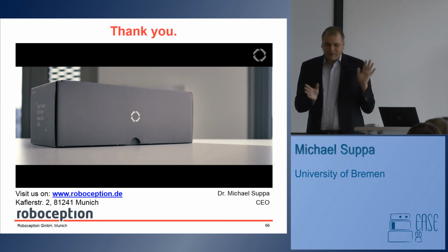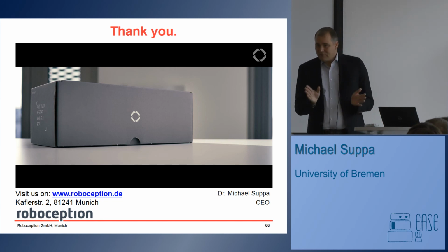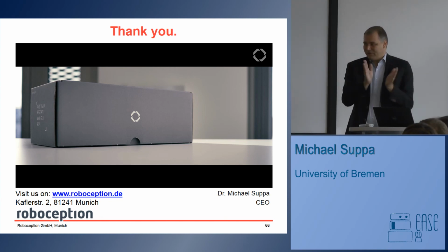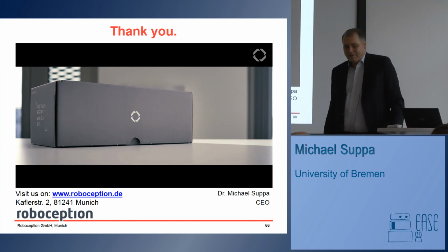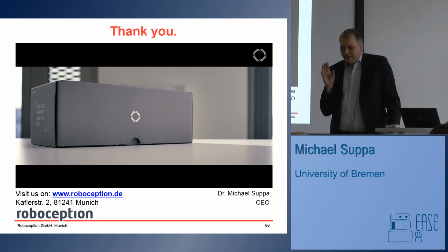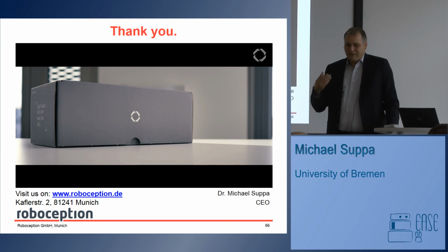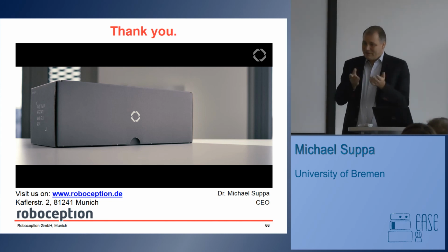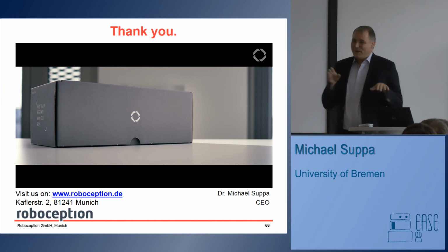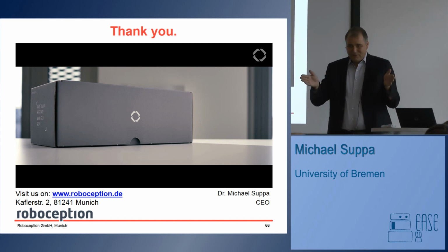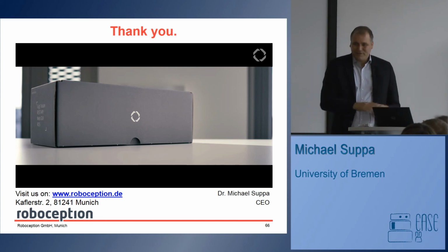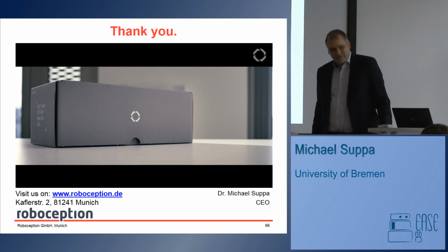Also, we have now an opening angle of about 60 degrees. Everything beyond 120 degrees is really costly. The lens price goes up a lot if you have wide angle cameras. And we wanted to have more or less the same kind of error over the whole field of view. If you do this differently, it's difficult for the confidence image as well, if you have high resolution here and lower resolution toward the border. So we wanted to make it simple. For most industrial cases, that is okay.